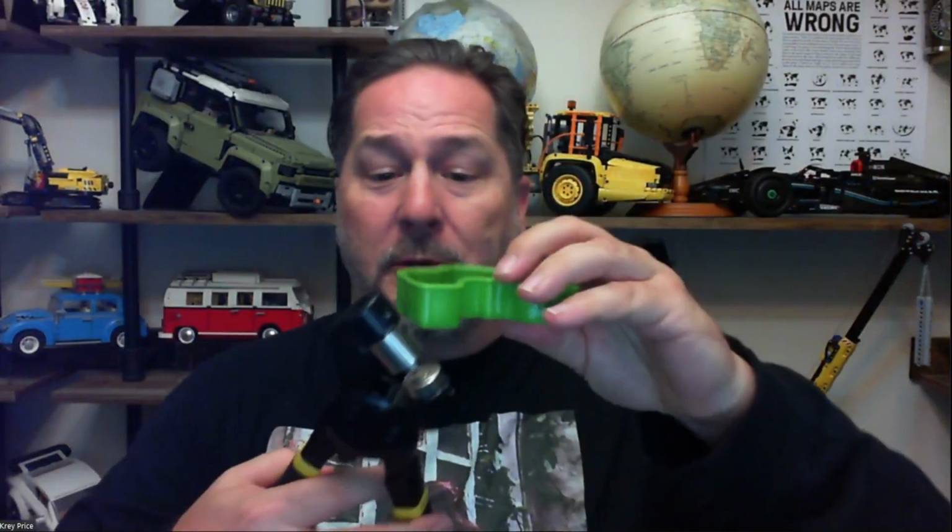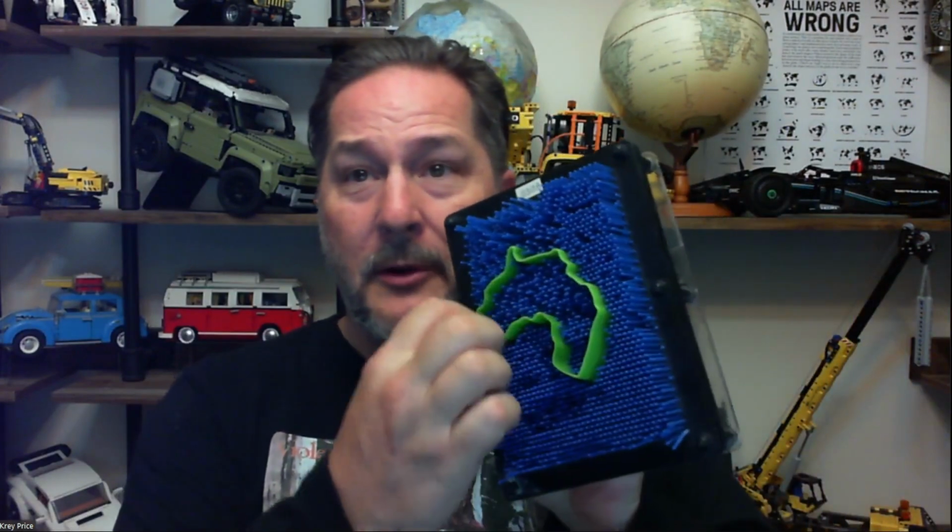we're basically taking this impervious perimeter that we've drawn over our terrain data. We've now discarded everything outside of it, and now we're just going to add water to that terrain. So to do that, we'll have to punch some holes in the perimeter, or the top, or the bottom of this thing. I'm not going to go ruin my cookie cutter for this, but if you use your imagination, that perforation will now let water in or out of our model. And that way we can see how it flows over the terrain features that are inside of this perimeter.